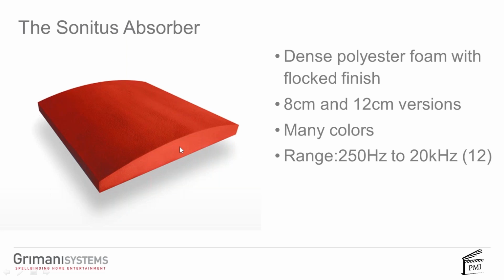So when you put this in your client's home, they're not going to be as annoyed as if it was a straight square chunk. To be fair, and to be real, because I don't like fake news, a straight square chunk would work better at low frequencies. The thickness that's lost over here for the sake of aesthetics loses a little bit of low frequency.